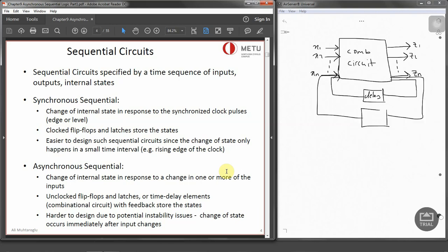We can have more and more which are coming out and going in, and each of them has their own delay elements. In this case, let's say this is Y1 and this is Yk, and the feedback that is going in as a present state is small yk and small y1. So k here represents the secondary variables, or the present states. And the capital K represents the excitation variables, which are the next states. The delay elements can be visualized as providing short-term memory for sequential circuitry.